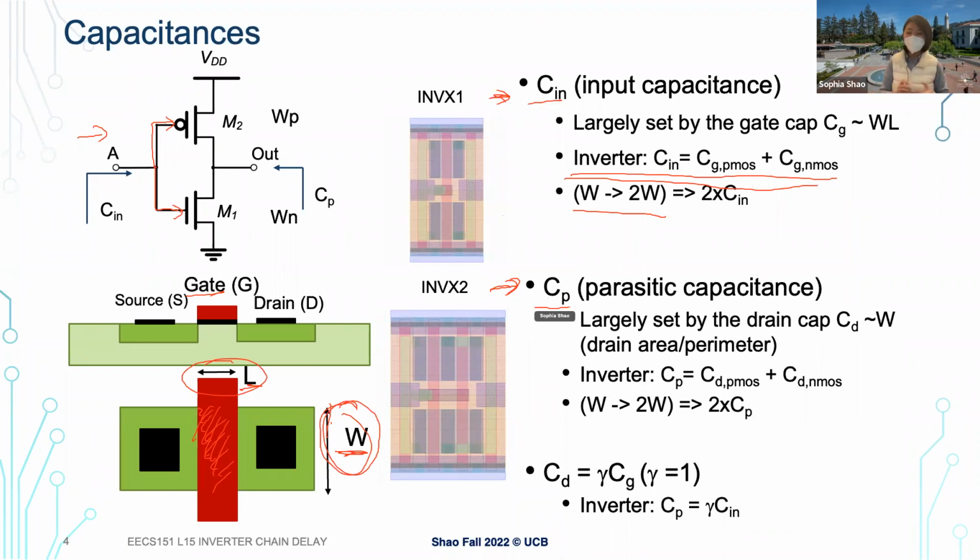We briefly talk about the parasitic capacitance. We mentioned it's basically the overhead. It's not directly related to functionality, but when we switch our circuit, we also need to charge this parasitic capacitance as part of our MOS design. When we think of parasitic, again, this is looking from the output.